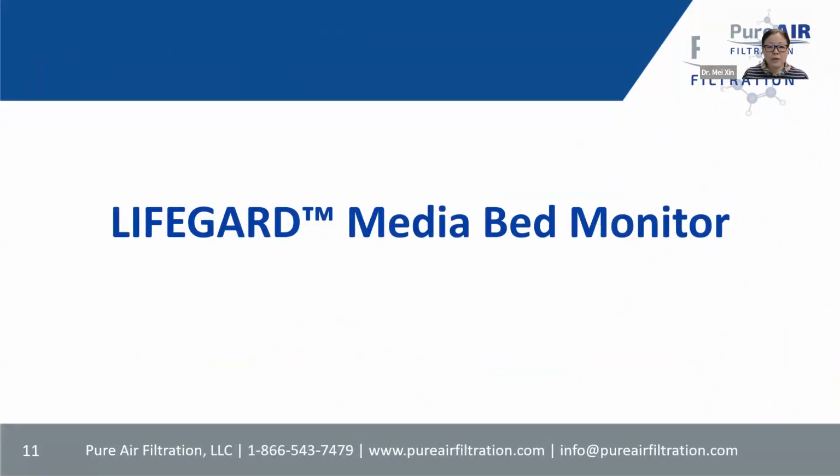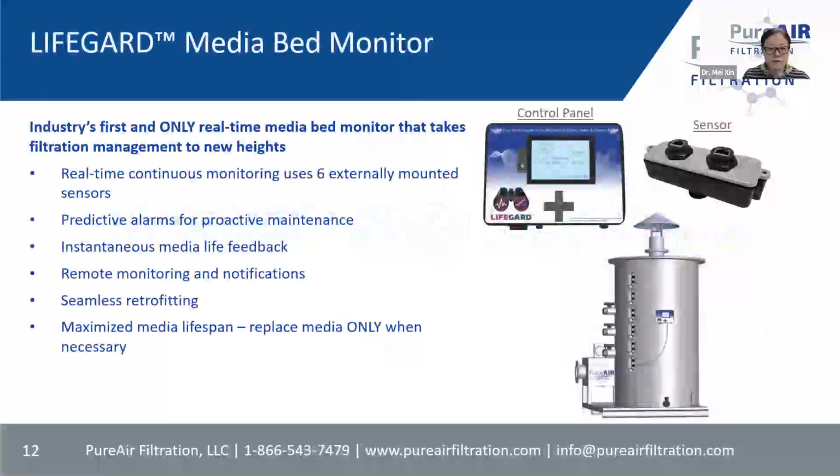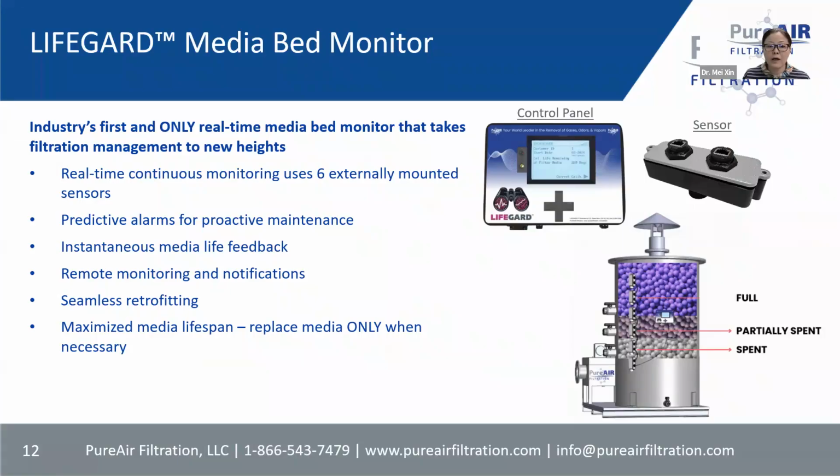We also have a more advanced monitor, Lifeguard, to monitor media bed performance. Here is a little demonstration in the lower right corner. You can see how the system works, and when the media is spent, how the mass transfer zone moves from the bottom up.